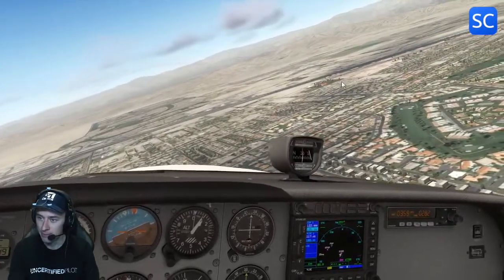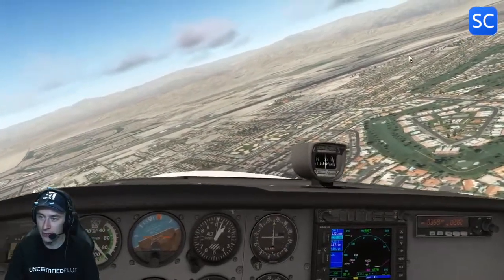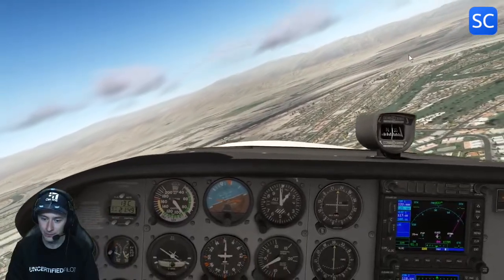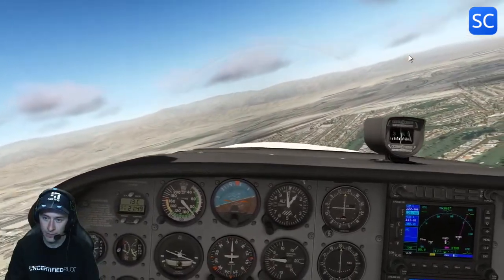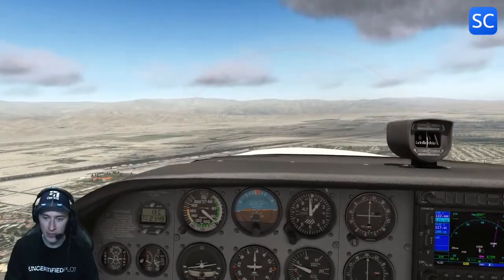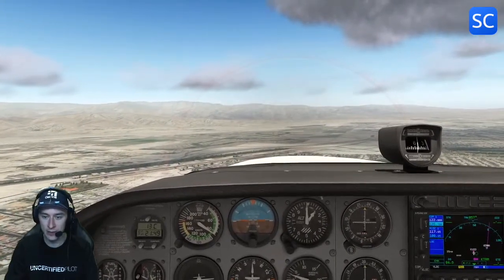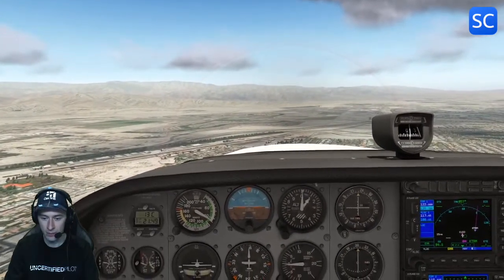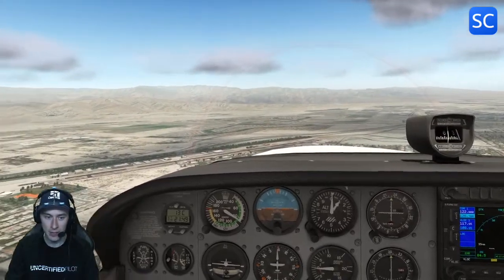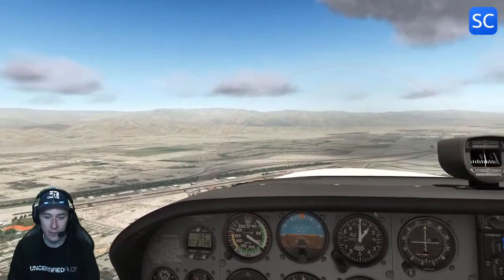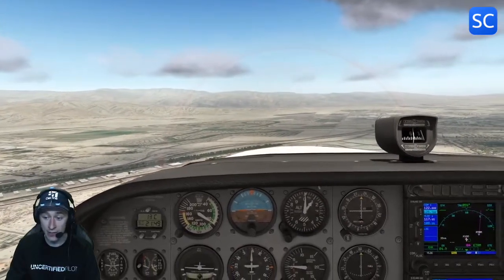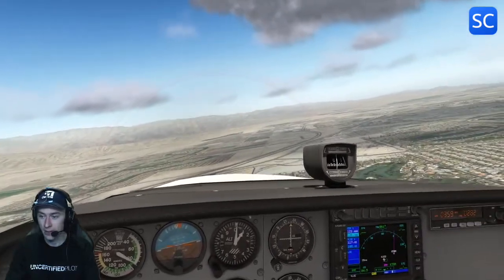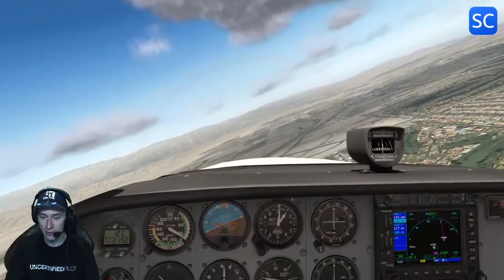And there's the runway. And we're now entering on the 45, right? 45. Bermuda Dunes traffic, Skyhawk Papa Hotel Tango Mike is on the 45 left downwind 28 for a full stop. Good. A little bit closer. Again, the distance from the runway is actually based on a very practical measure, and that is in case of an engine out, can you still make the runway? Usually a half or 1 mile from the airport.